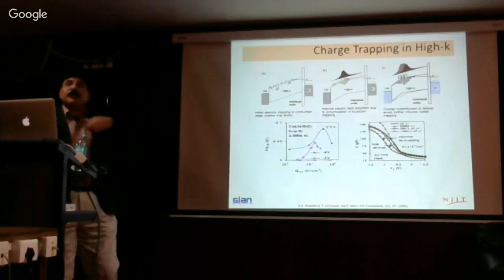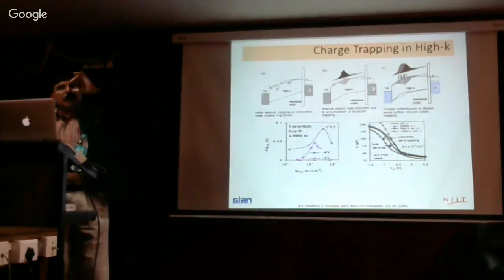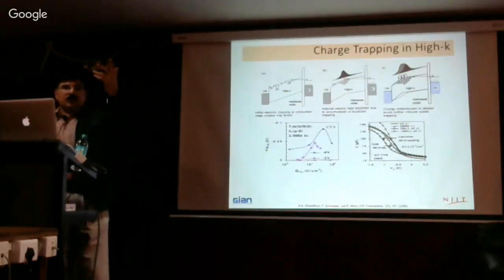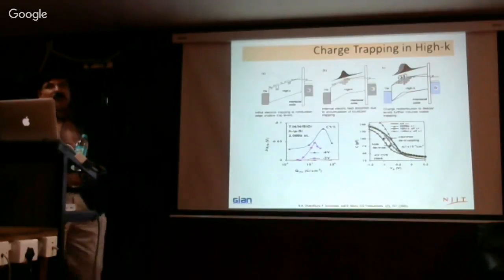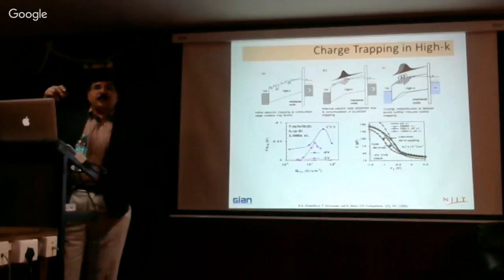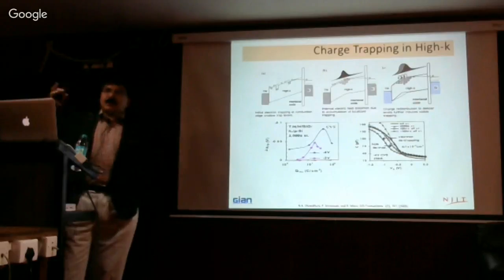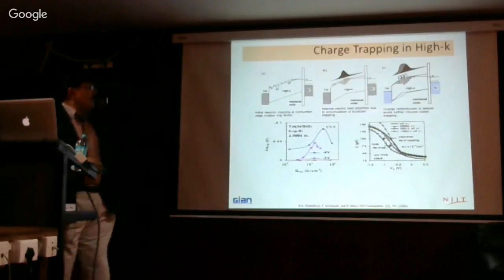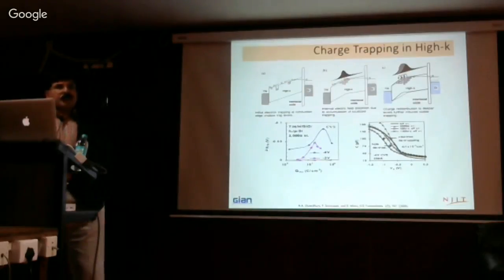Or if you give a reverse potential, let's say if you started with the stress from gate to substrate and you change it to substrate to gate, then a lot of these things actually move back. But it's very difficult sometimes, depending on the voltage level, you may not come back to the original place that I was saying because of the detrapping. If you have all the defects in the shallow level, then you have a very good chance that you get detrapping.